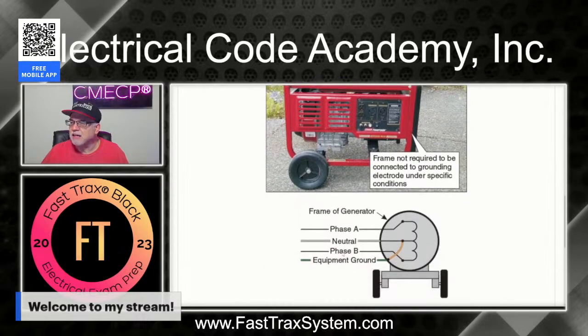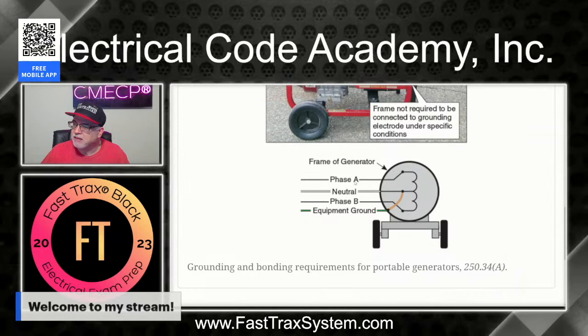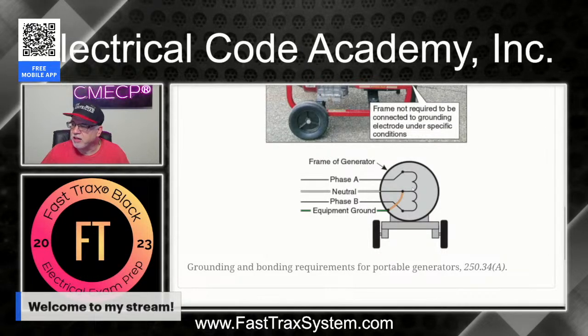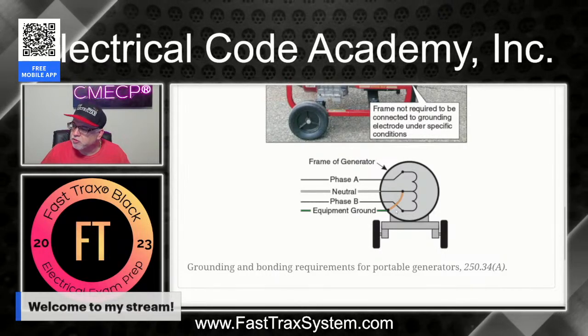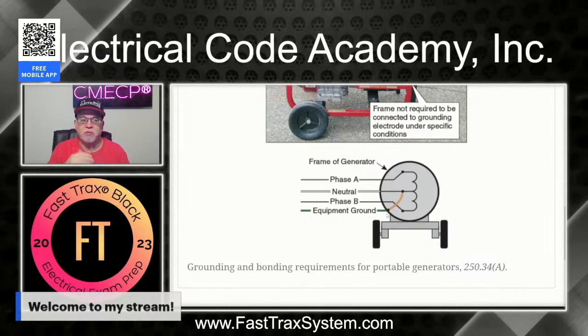All right, what does that look like in an illustration? So here's that generator right here. This is the generator above, drawn out in an illustration. Here's phase A, here's phase B for the 240 volts. Here's the neutral, so phase A to the neutral is 120, phase B to neutral is 120. Here's all of our setup. Here is your connection right here that creates this bonded generator over to the frame. So the equipment grounds are connected to the neutral point. Everything in this frame is connected to the neutral point, all meeting the requirements that we just saw. No electrodes are required for this portable generator. Make sense so far? Okay.